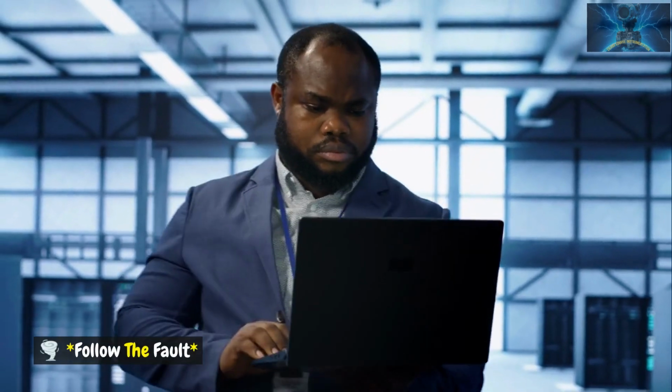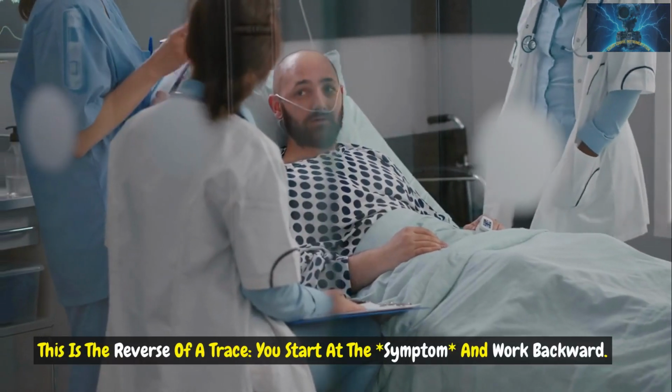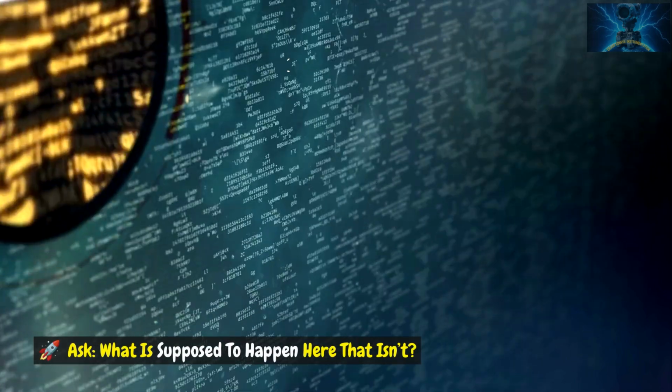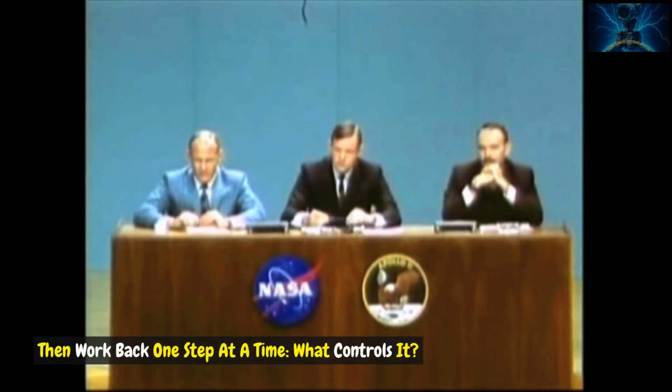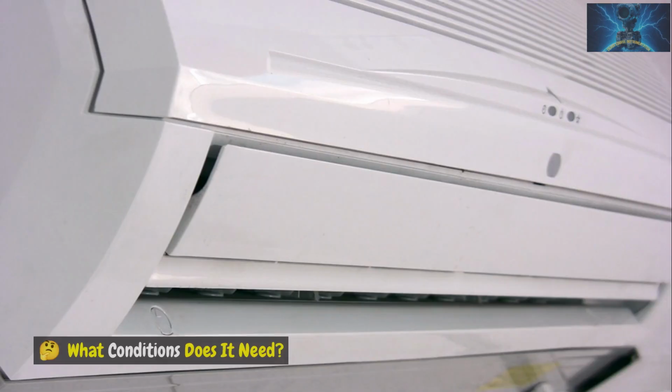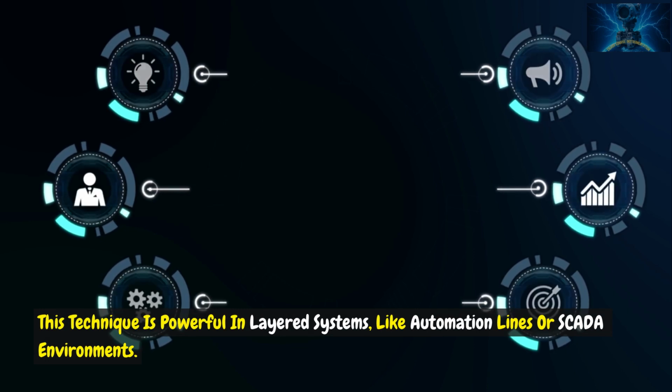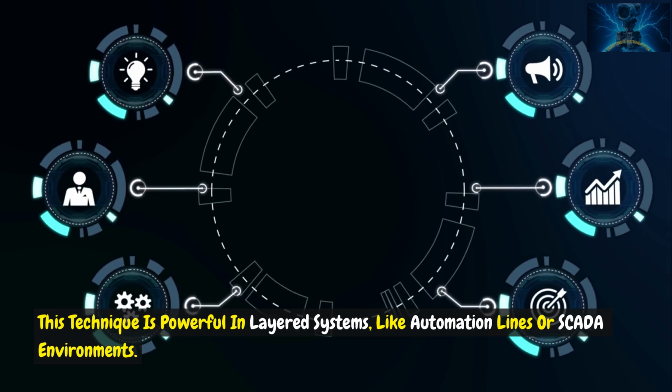Follow the fault. This is the reverse of a trace. You start at the symptom and work backward. Ask, what is supposed to happen here that isn't? Then work back one step at a time. What controls it? What powers it? What conditions does it need? This technique is powerful in layered systems, like automation lines or SCADA environments.